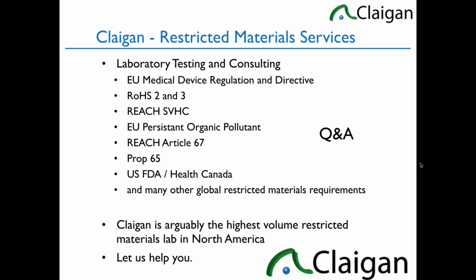For a medical device with electronics, the disposables that are consumed in the lifetime, with a shorter lifetime than the product, that are not electrical in nature, are not in scope of RoHS. So if you have tubing that is regular, it's a consumable as part of your device, it's not in scope. You have a printer head, a printer cartridge. The cartridge, the electronic part, is actually in scope. It's electronic, but the ink is not. That consumable is not. So any non-electrical disposable is out of scope. If it's electrical in nature, it is in scope.